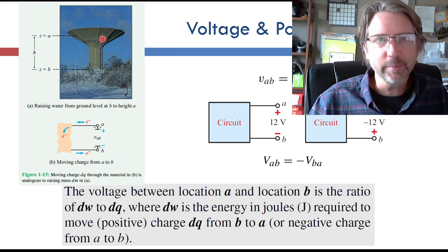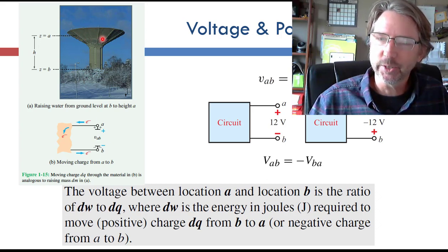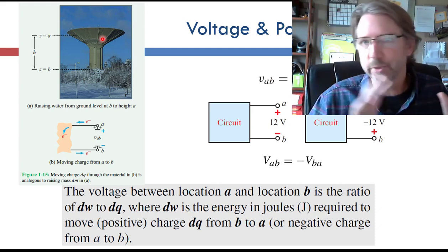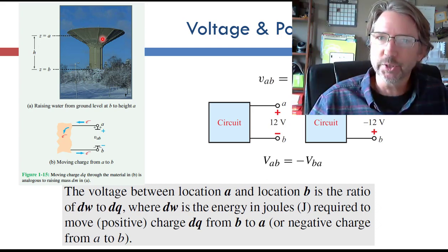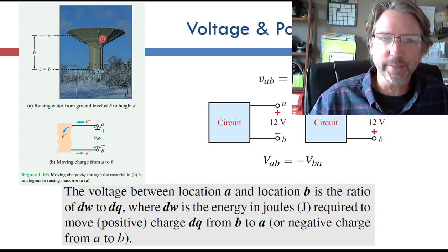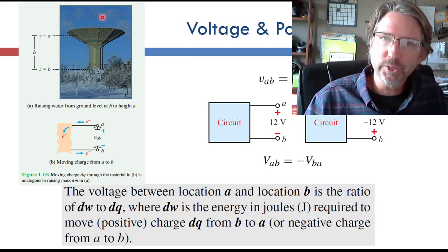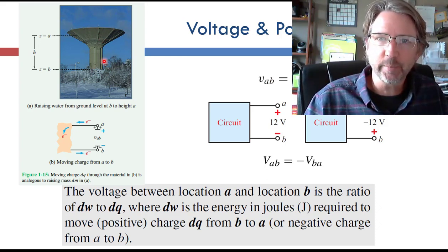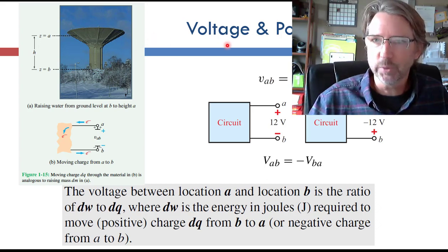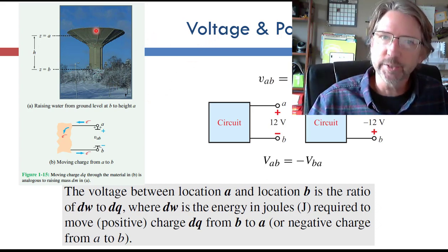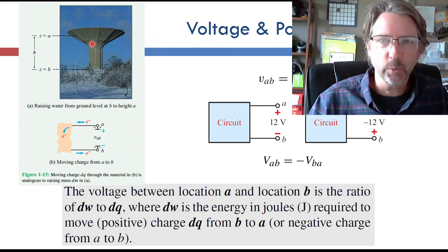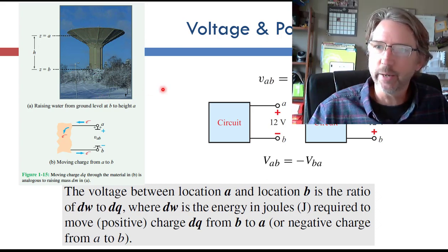And so a lot of the times there's a hydraulic analogy in electronics, because the equations for hydraulics and the equations for circuits are the same equations, and so that's why it's analogous. So potential energy, hydrostatic potential, is a lot like voltage. It's how much work it takes to put water up there, or how much work you get out of the system if you let the water out.